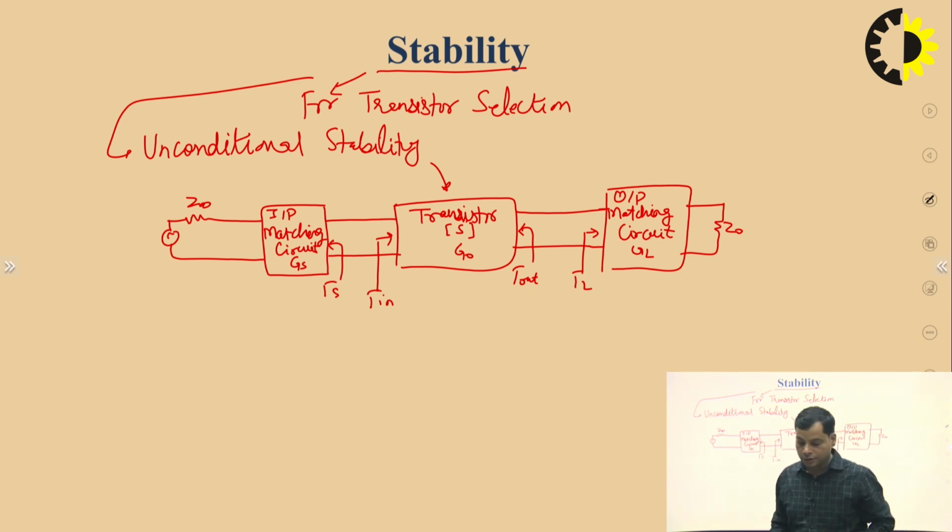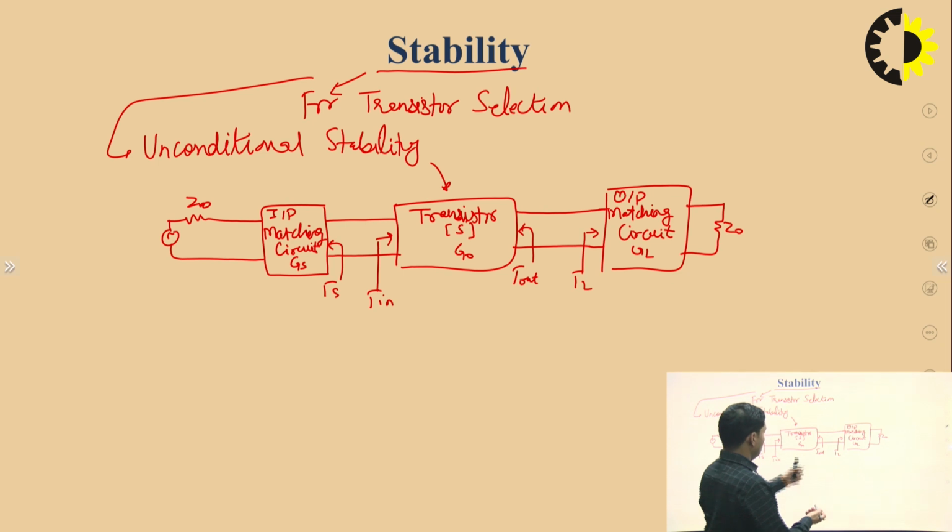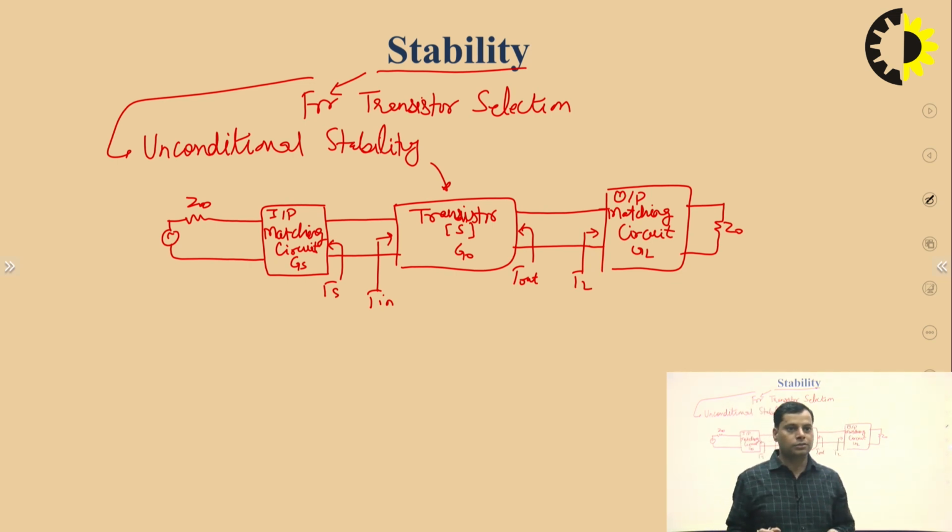And in a similar way, from the Smith chart we can also find out the distance of the stub from the transistor to the output end, and how much length of stub we have to connect. In this way we can design an amplifier circuit with the help of the Smith chart. So this is the simple microwave amplifier designing concept.